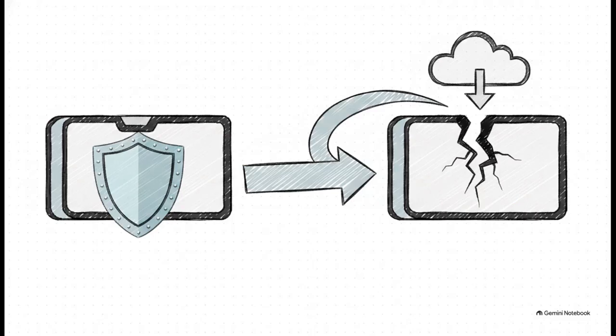Now you might be wondering, what happens if an over-the-air update fails mid-download? The way automotive engineers solve this is just brilliant. They use a dual-zone flash architecture. It's essentially a digital time machine. Bank A stores the historical, healthy software version. Then, during an update, 100% of the new firmware gets written into a completely separate Bank B. Bank B is then put through rigorous SHA-256 cryptographic hashes and error correction code checks.